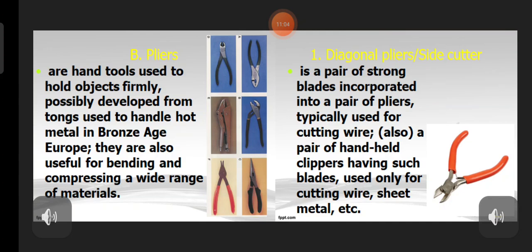Diagonal cutting pliers are the most commonly used cutting pliers. The jaw shape allows cutting flush with the surface. Locking pliers or vice grips clamp onto and hold the part, while snap ring pliers have sharp, pointed tips for installing and removing special clips called snap rings.